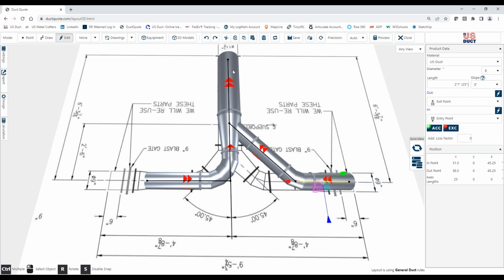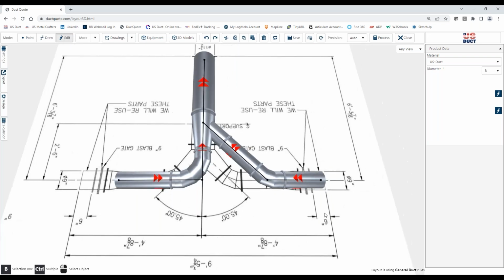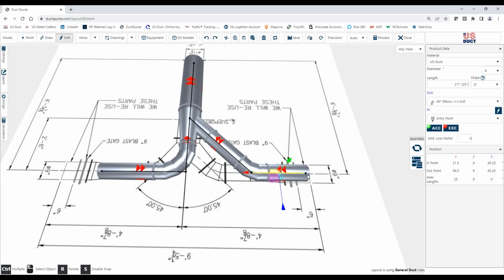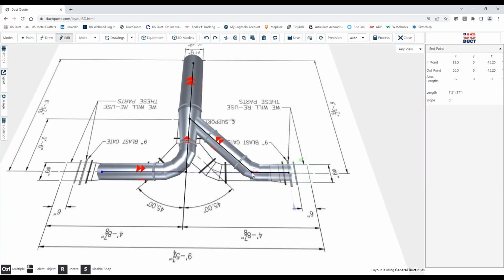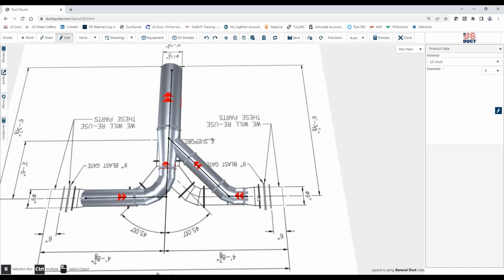we didn't have to move this end. Let's say that's one of the criticals. And we didn't have to move these two opposing sizes, but we did have to change how we handled the connection there. And this all now works with standard size. And if we needed to change this back, we could bring this back just to the elbow, it looks like. And you can see that we're now finishing at those reducers, and that would work, right? So that's what we mean by a combination of an elbow and a branch.